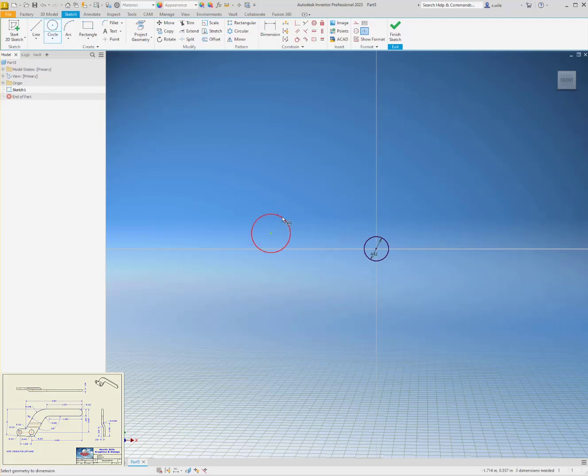And then the back side is 0.313. It's horizontally aligned and 1 apart. And then I think I'll just draw the rest. Now that top dimension 4991 goes down into the fillet here, but it shows the extension line, so that's going to where they intersect. So I'm not going to draw that fillet, and I'll add that fillet afterwards.